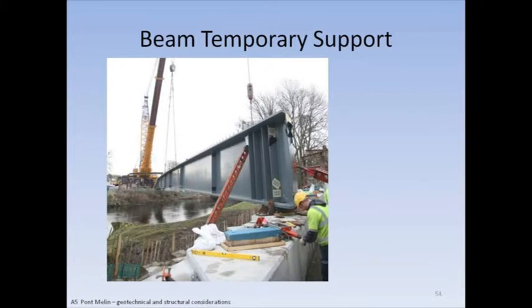During the design stage, the intention was that the beams would be landed onto jacks, so there would be that variability of height. The contractor rationalised things and took a gamble that settlement wouldn't be too significant or too differential, and chose to land them on hardwood timber blocks with a little bit of visqueen on top.